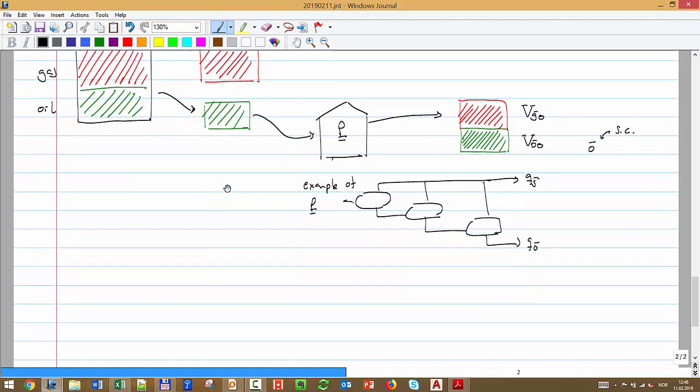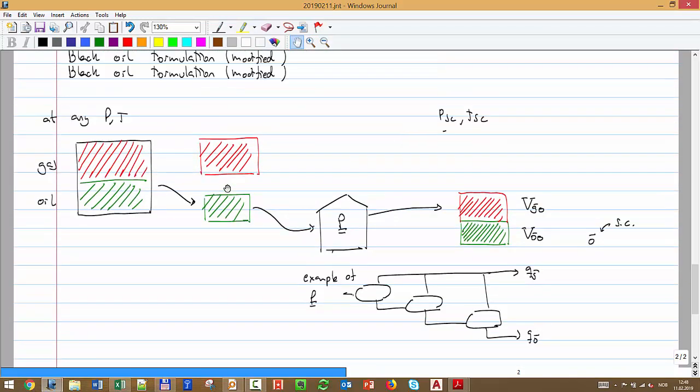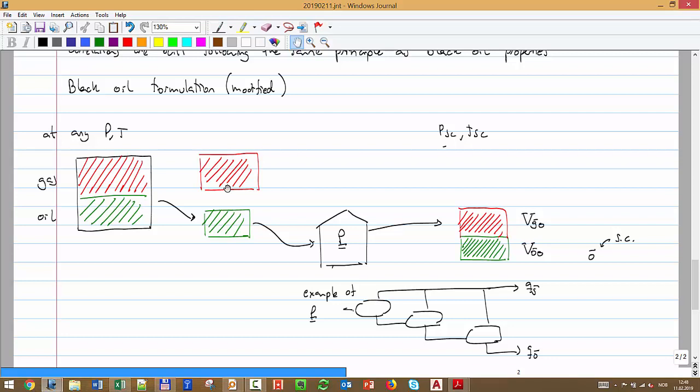Okay, and then petroleum engineers like to find a way to make the relationship easy. Typically I measure these two in the separator. Then I want to calculate what the local conditions are, what the volumes are at any given pressure and temperature. With the volumes, I can calculate pressure drop, erosion, and temperature calculations. I can do many things, but I need the volume to get the velocity.